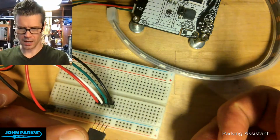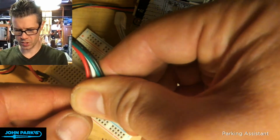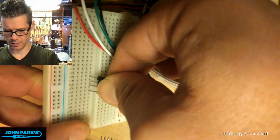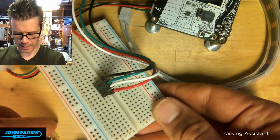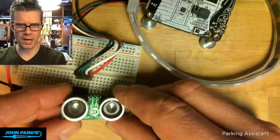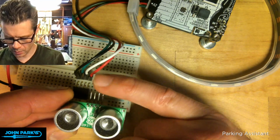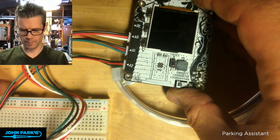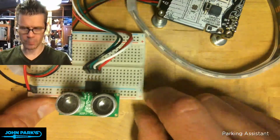So what I'm going to use is a little set of header pins that I've bent, and I do need to flip the orientation of these cables. So I'm going to take those and flip them around. Sorry, it's probably just my hand in the way of the camera. There we go. And if I plug in like that, you'll see here I'm matching up the voltage, trigger of the ping, echo, and ground. So that lines up with that. And then I have those plugged into power and ground and a couple of pins, A1 and A0. It requires 2 digital I/O pins so that I can send and receive.